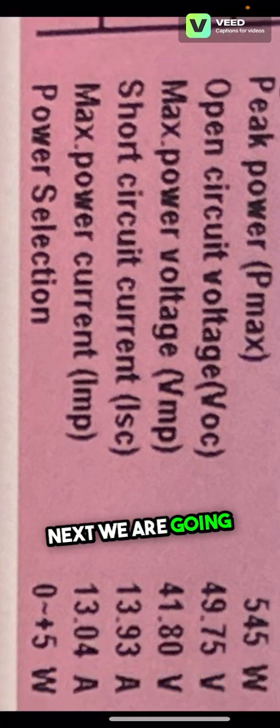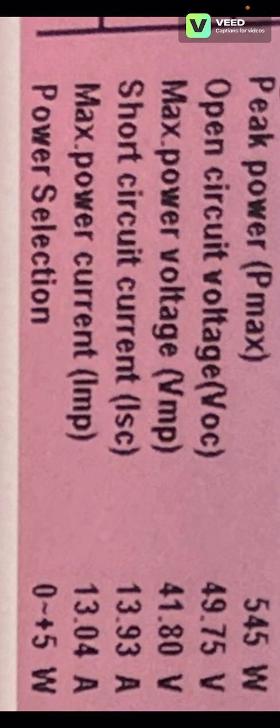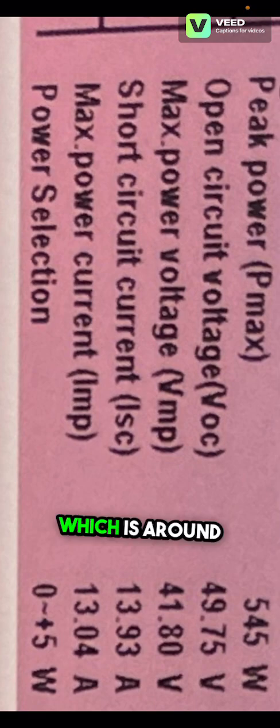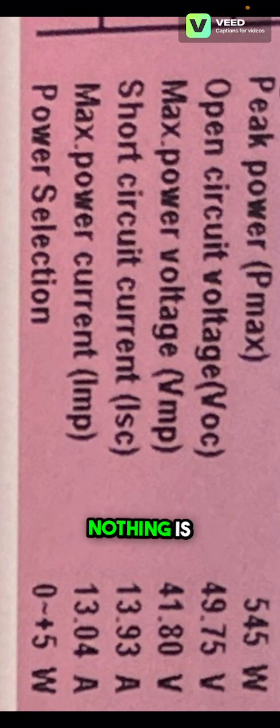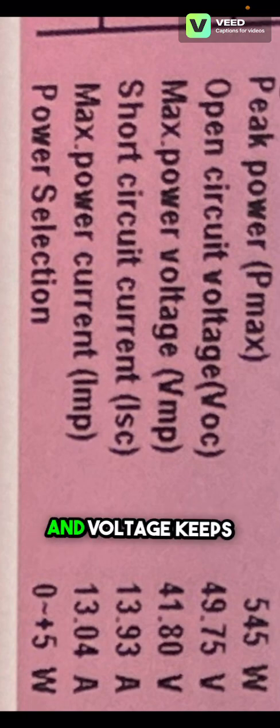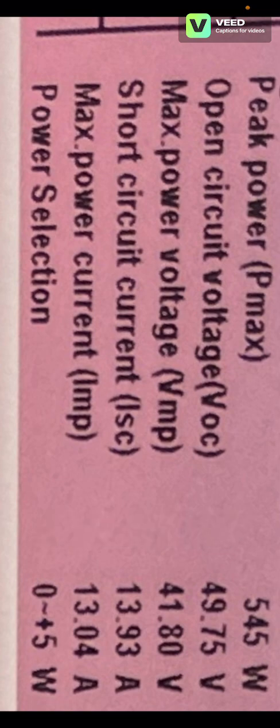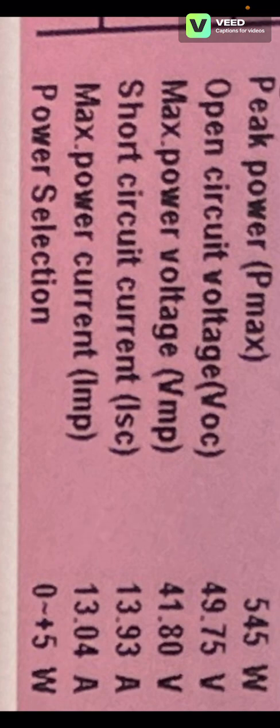Next we are going to talk about open circuit voltage, which is around 49.75 volts. This is the voltage you will get when the panel is kept in sunlight, but nothing is connected to it. This value is very important when we design strings, because many panels are connected in series and voltage keeps adding. That's why this is open circuit voltage.